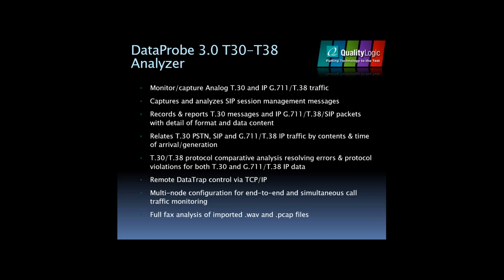T38 was an attempt to compensate for that by taking the T30 messages and turning them into digital IP messages in T38. So each T30 message has its T38 equivalent. The message transition is sent across the internet and then turned back into T30 at the far end.